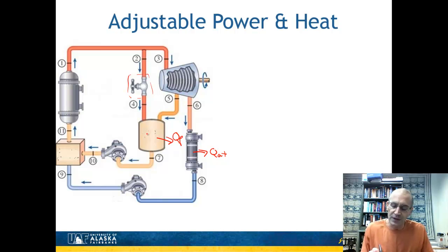And the process heater is here, and it's actually got two inputs. We've got this superheated steam that's just coming through a throttling valve, and then usually we take some off the middle stage of the turbine and we mix the two, and this is the process heater. It produces heat, and then usually the material becomes condensed so that we can run it through a pump. So it's a little more complicated. We have two pumps now. We've introduced the process heater. The throttling valve doesn't really add too much complication, and we've gone from a single stage turbine to a two-stage turbine. But as we'll see when we do an example in a little bit, this can be dialed up and dialed down fairly quickly just by simply turning that valve.